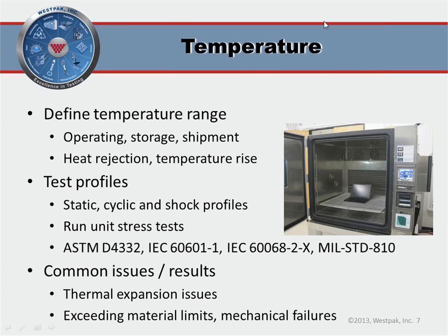The storage conditions may be minus 10 to plus 45 degrees C. And with many products like this, the most extreme thing you may see is the shipment environment, which can be minus 30 degrees C up to plus 60 degrees C. Although, in fact, there was a study done a few years ago showing that a hot trailer going through the desert can get in excess of 72 degrees C interior temperature. Also think about storage conditions like being inside a hot car. That can also get up to that range.